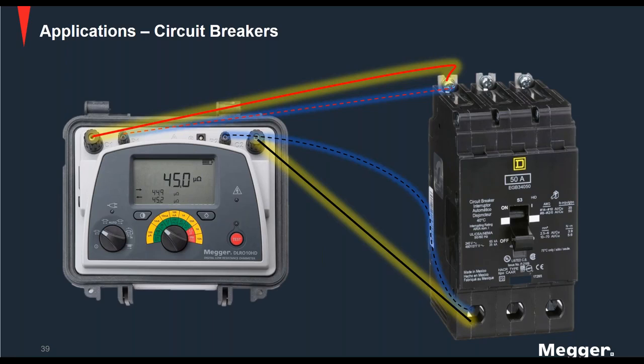And note here that the C1 leads are above the P1 leads, which we have been discussing, that's the ideal way of measuring resistance, right? On the same, if you look at the bottom, you have the black lead that's solid with a yellow glow. That is the C2 lead, the second current lead. And then you have the P2 lead with the dashed lead with the blue glow.